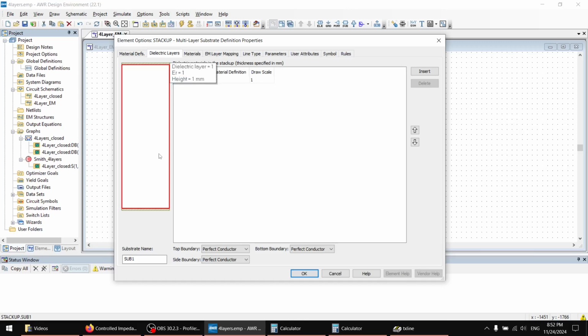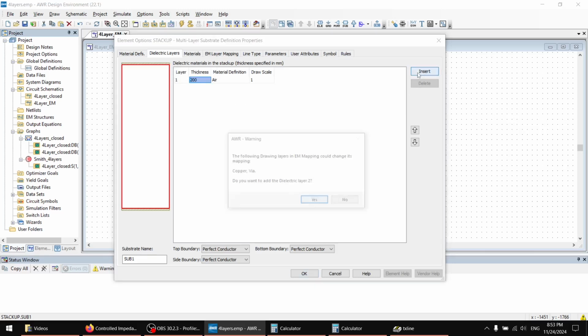And this view is basically our, let's say, stackup, right? So we will see, as we add materials, more and more. So first is air, and I will put, let's say, 200 millimeters, so like 20 centimeters away from the board. It includes our simulation above it. And if you have, for example, some sort of metal enclosure and so on, you can add it later on to these materials and include a much smaller, for example, air thickness.